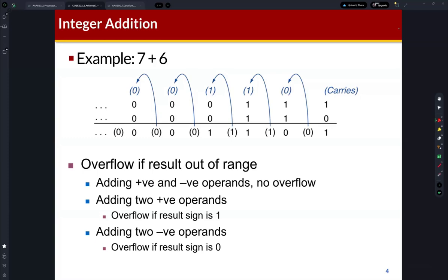If you see the RISC-V instructions, you can find that RISC-V includes the add instruction and the sub instruction for the R-type instructions. But for the immediate instruction, RISC-V has only addi. Why?